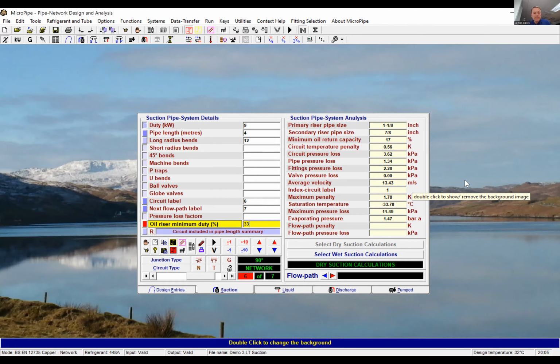So where I was going with this is the lowest minimum duty I would ever give, even if I've got 8 cases on that run, would be 25, because in a 24-hour period, generally the cabinet duty is based on an 18-hour run time.